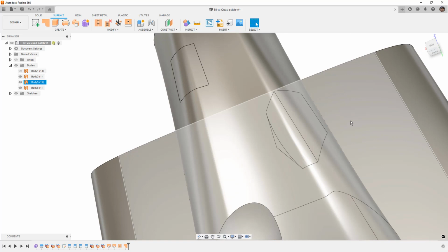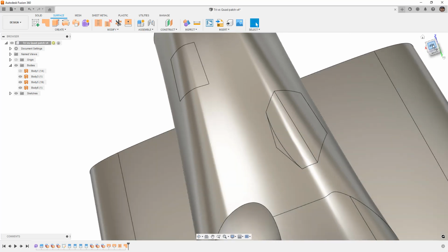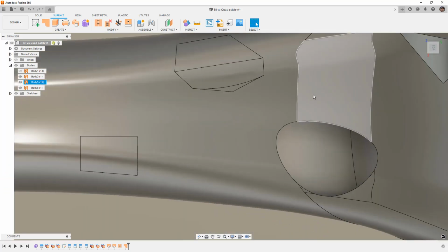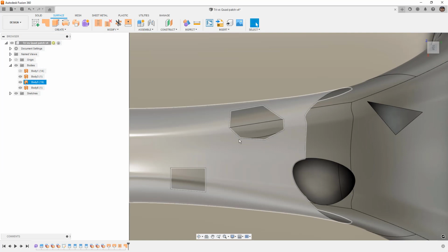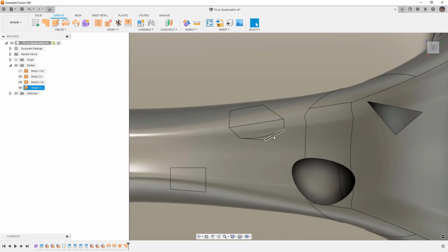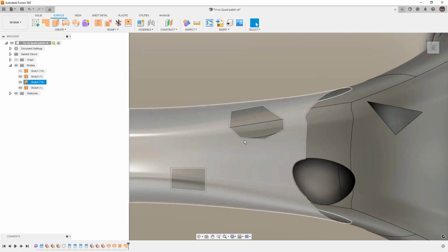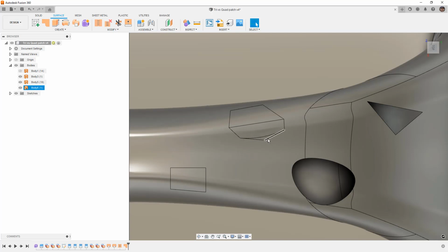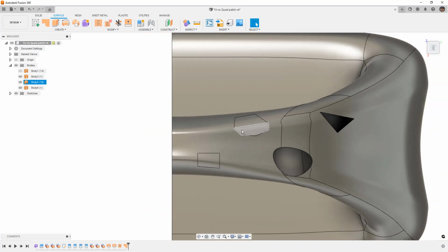The other option that we have, which is probably the way that I would approach this, is to create a better opening. So cut away more of the surface just to make sure that the inputs are better. So for example, I might create a spline cut here instead of having these two edges so that I could use it as a rail and build this with one loft. So that is another option. It's always a valid way to go.